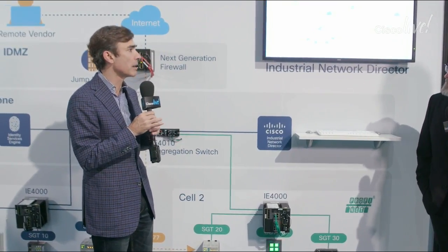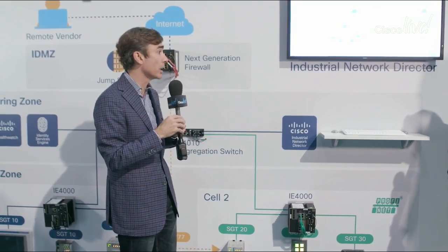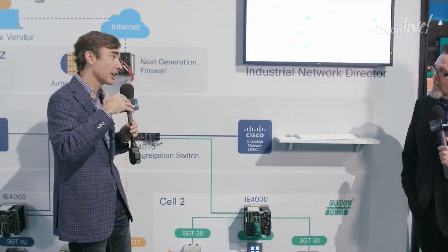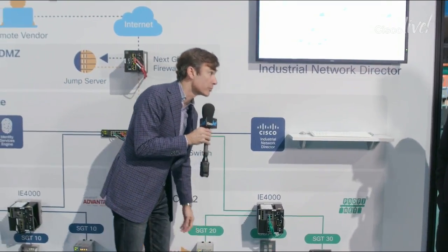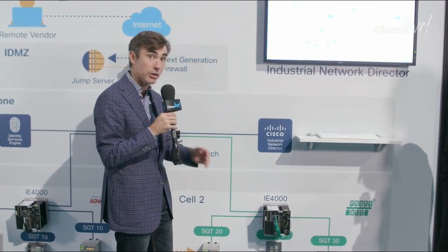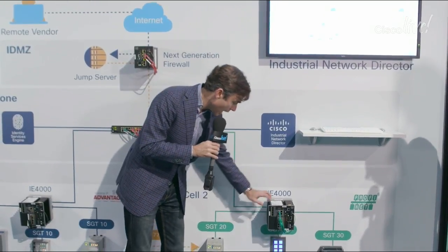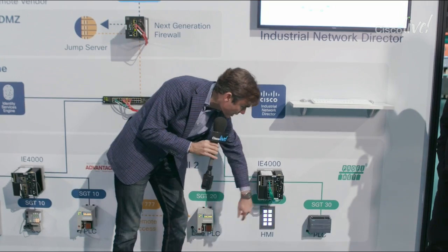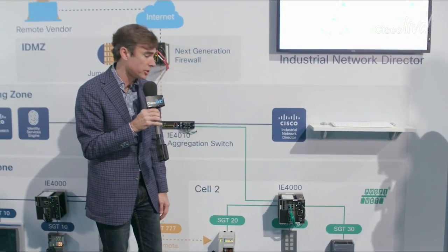And that was previously a big barrier to bringing IP down to the plant floor. If we start opening up our systems, they could be hacked. What they're finding is actually any of these types of systems are vulnerable to attack. So what have we done to ameliorate that? Now we're looking at the traffic between the switch, and in this case the PLC, and we've got that segmented by these different segmentation tags.